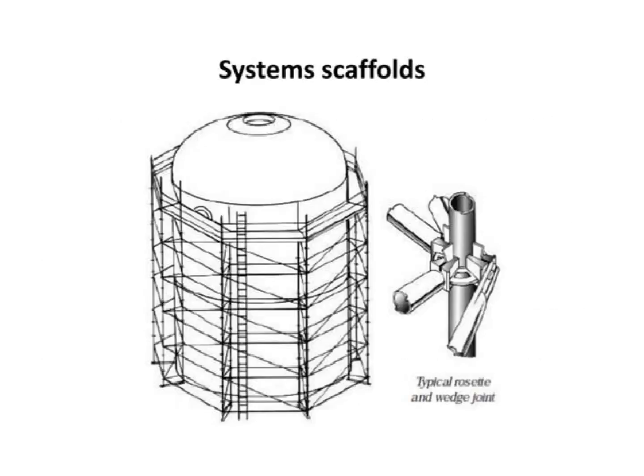Accidental slips, trips and falls are one of the most common causes of injury in the workplace. In order to reduce the risk of these accidents, it is important to take the necessary safety precautions, such as maintaining a tidy work environment, using proper footwear, and making sure that ladders are placed on firm, level surfaces. Additionally, it is essential to use appropriate edge protection, guardrails, and other protective measures when working on or near fragile surfaces. By taking these necessary precautions, we can create a safer work environment and limit the risk of accidents occurring.